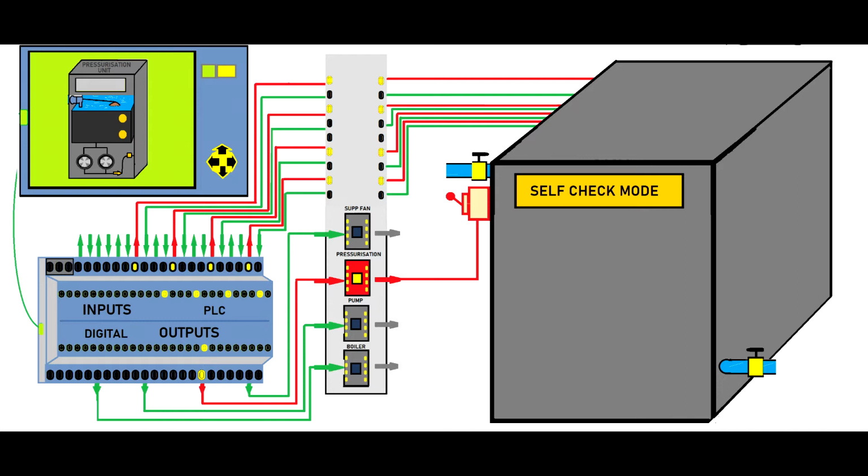If the pressurization unit is healthy, the color will change on the HMI and the system will be ready. This is good news because it's fully functional and we have no alarms. All the inputs are coming back into the PLC, and the HMI display tells you that everything is standby, ready to run. So this is good news.